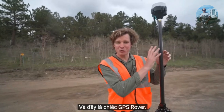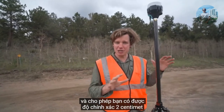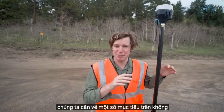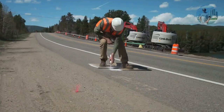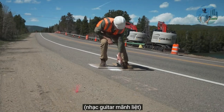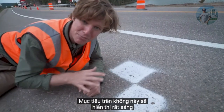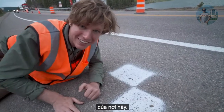And this is the GPS rover. It's communicating with the base station at all times and enables you to get 2 centimeter precision on all the data it records. Now to tie this into the sky, we need to paint some aerial targets that will be visible to the LiDAR data recorded from the drone. This aerial target will show up very bright in that LiDAR data. Now let's record the accurate location of where this is located.